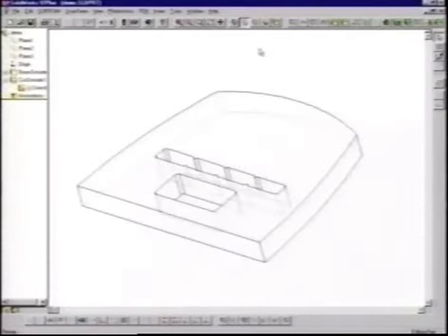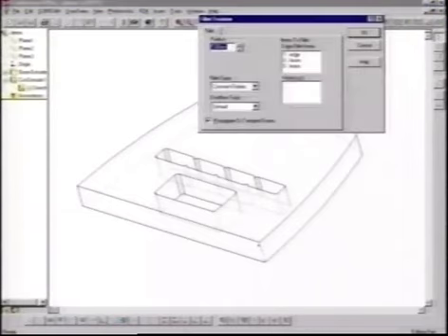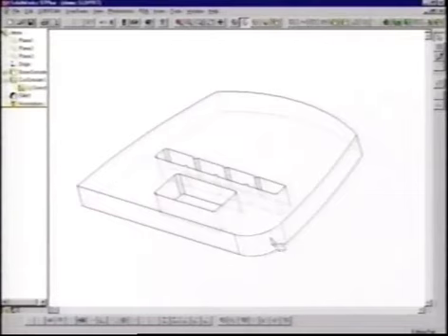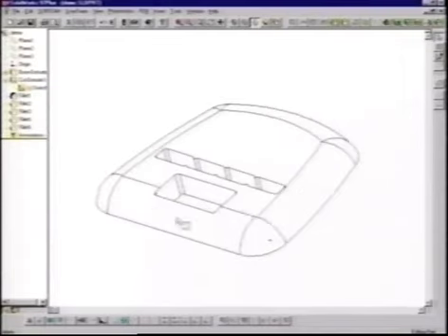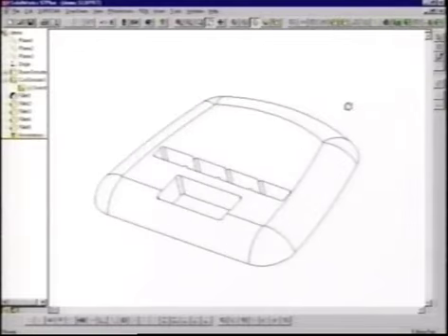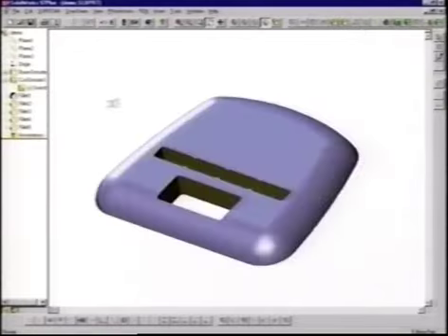The next thing we'd like to do is let's remove the sharp edges that exist within the part. So to do that, Joe's going to add a fillet feature, and he's going to start with this lower corner. Now we want to ensure that the fillet is the same in all four corners of our console design, so Joe is simply going to drag and drop that fillet from one corner to the next. And it's just that simple, again, because it's a Windows application. What Joe's doing right now is he's taking that fillet and he's dragging it onto the front edge of the part as well. So that this way everything is tied together right on the part.